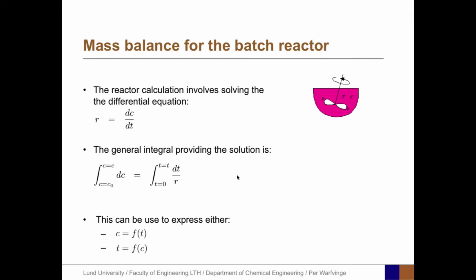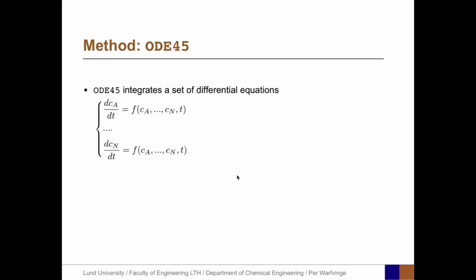Numerically, we can either use these equations to solve for c as a function of time or t as a function of concentration. ODE45 is a MATLAB function that is used to integrate a set of differential equations, and they can be coupled, so that the differential equation describing the change with time for Ca can be a function of other concentrations of substances in the system.